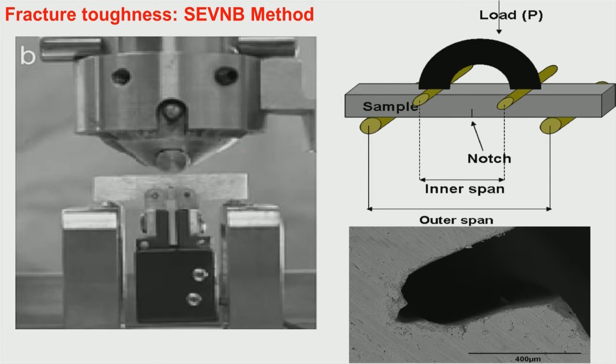And this is how one can measure it experimentally. What you see here is a 3 point loading assembly, and this is the 4 point loading assembly. If you apply a load P, it is distributed at 2 arms, so this is P by 2 and P by 2. Every action has an equal and opposite reaction. So, if P by 2 load is there from the top, P by 2 load would also be experienced at the two rollers kept at the end of the outer span.